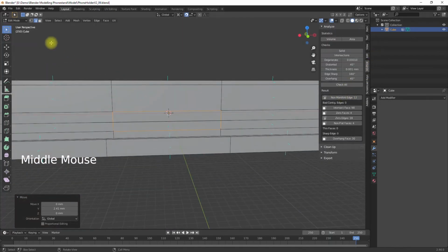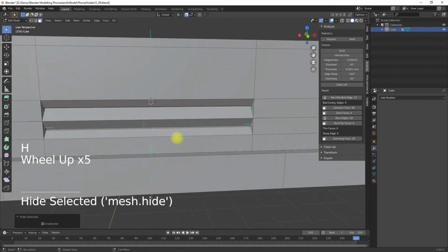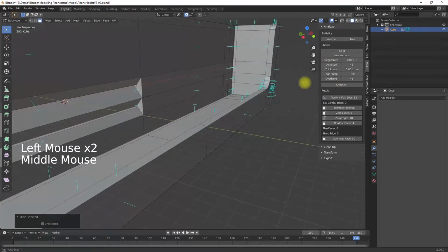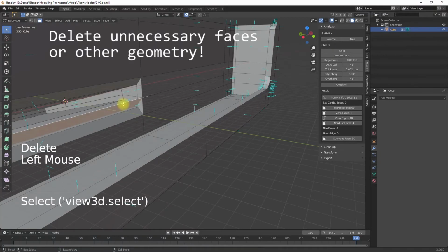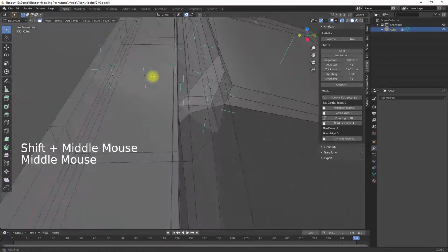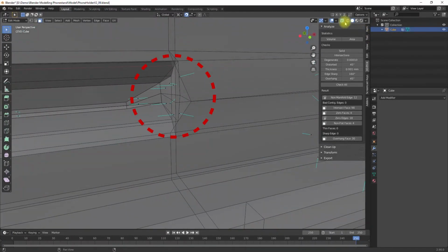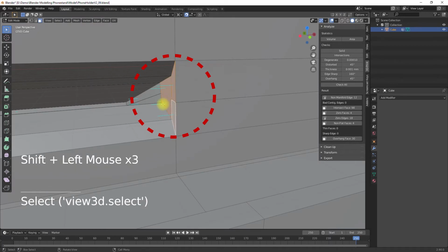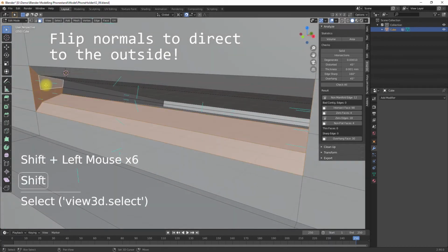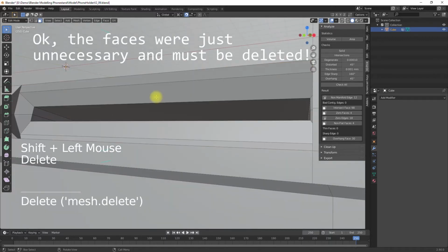Additionally, duplicate vertices should be found and deleted. The normals of the faces should be correctly aligned and point outwards. These errors can cause big problems for 3D printing, although many smaller problems can be solved by current slicer programs during the slicing process. Some of the errors in the model can already be corrected explicitly by special functions of the slicer programs.